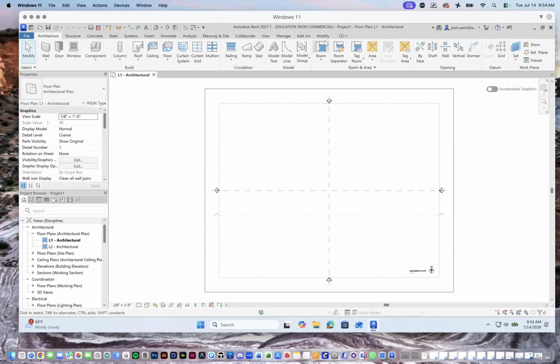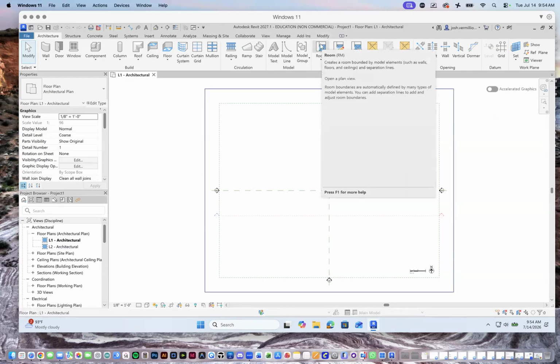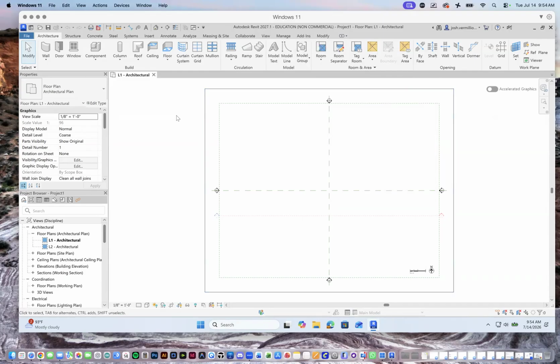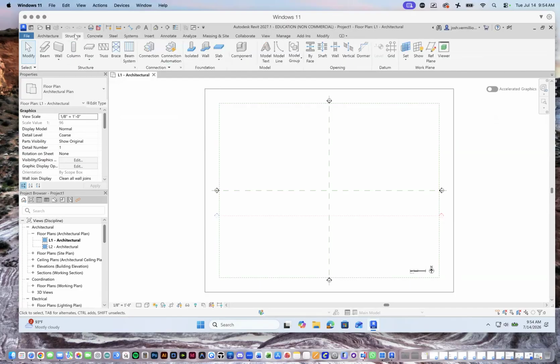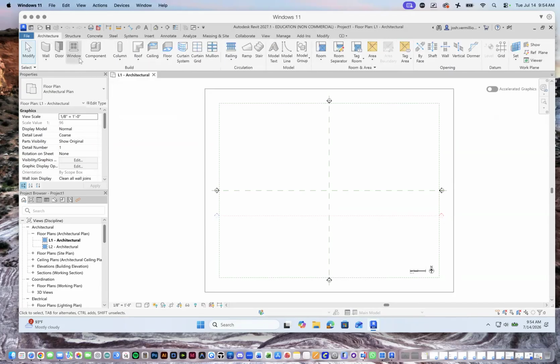And when we start to select things, you'll understand that there's a modify tab. So we select something, let's say a floor, and it'll take us to the modify tab and it'll say, what do you want to do to that floor? Why are you selecting that? Do you want to stretch it, put a hole in it, move it, rotate it? What are you trying to do here? Right. So anyway, there's a lot here to dig into, but suffice to say, as we start to create new things in Revit, things like concrete, structural columns and beams, architectural floors, walls, doors, curtain walls, etc., ramp stairs, railings, whatever, we'll go back and forth between a lot of these tabs.